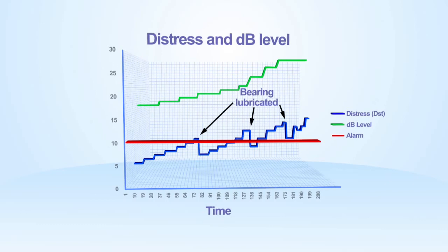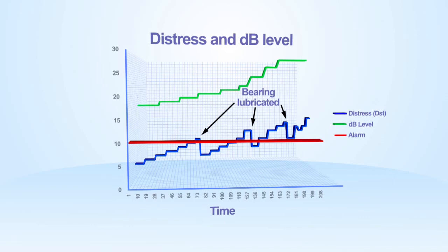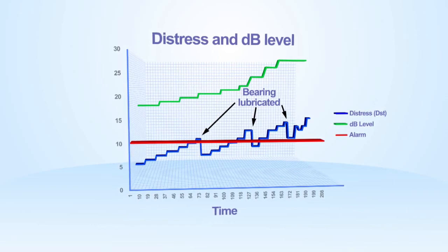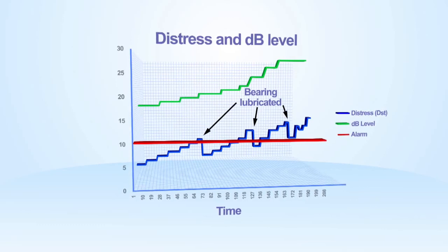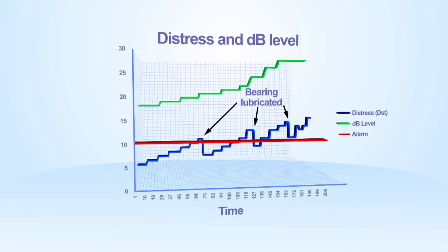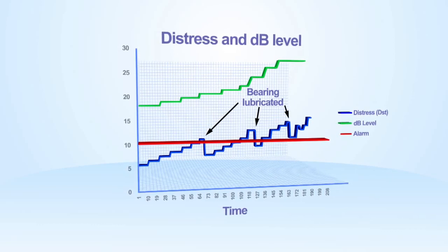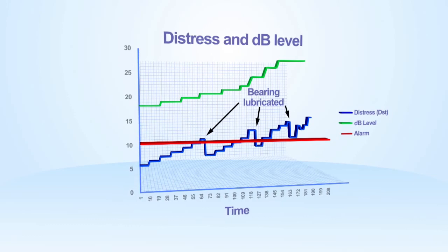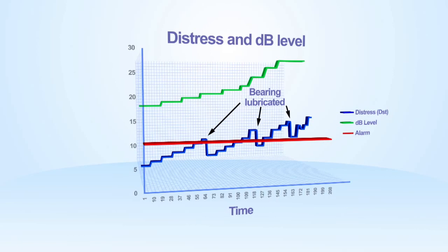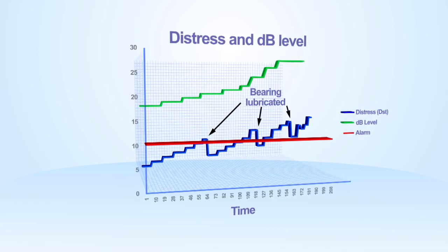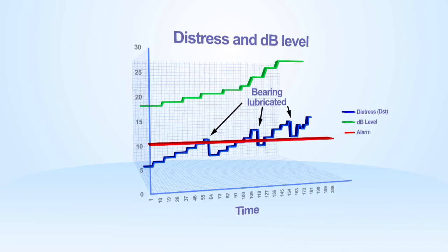dB level quantifies the frictional activity taking place and cannot be easily estimated. The level of dB is dependent on the speed of the bearing, but only increases as wear increases for the same rotational speed. Usually, the user would take a first reading and trend from that value or compare to a similar machine of similar age doing the same job. By trending this, the user can monitor the speed of degradation. A rapid increase in dB level is normally the final warning prior to bearing failure.